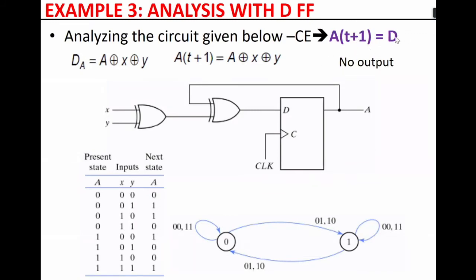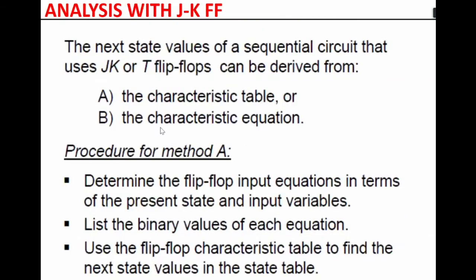You've been given an equation of the next state of a D flip-flop as a function of the input. That is what you call a characteristic equation. So you just derive what is at the input and substitute it into that equation. It will become interesting when we look at the other circuits. I'm still insisting, we are done with the analysis. We're just looking at examples, different configurations, but the procedure still remains the same. Now, the D flip-flop is the easiest.